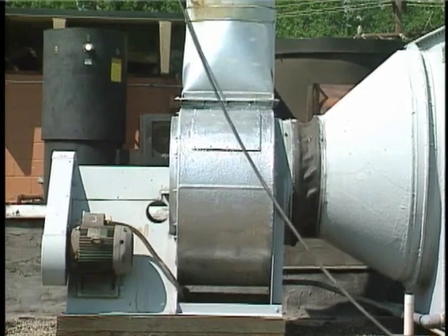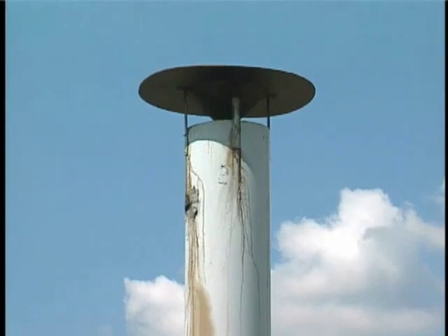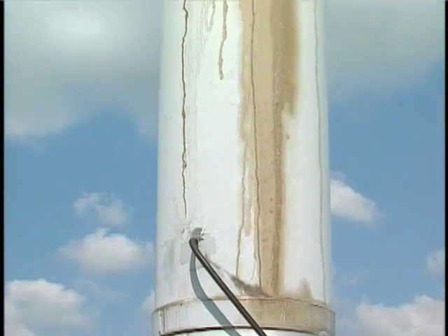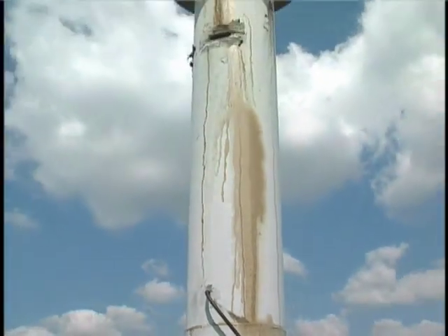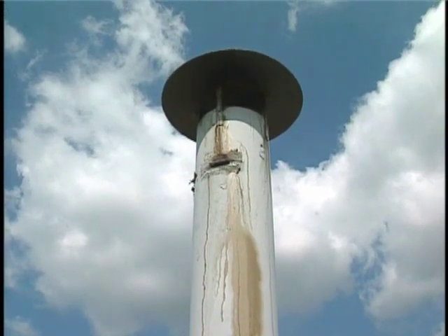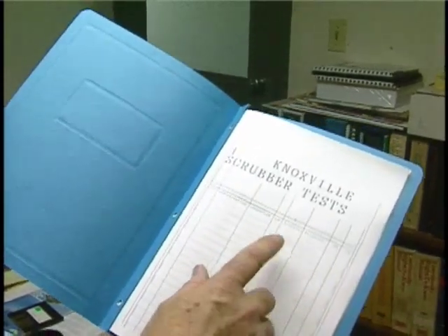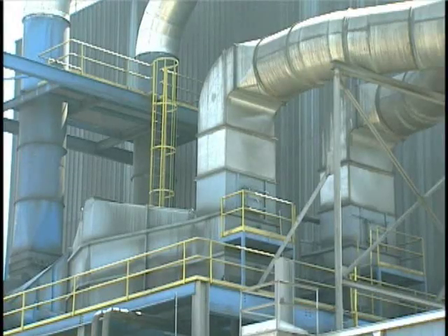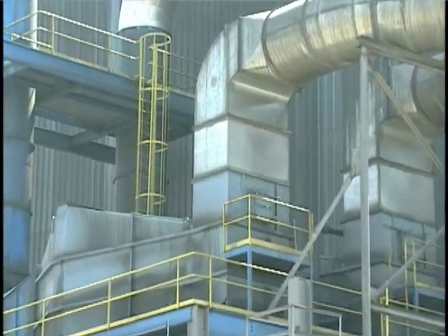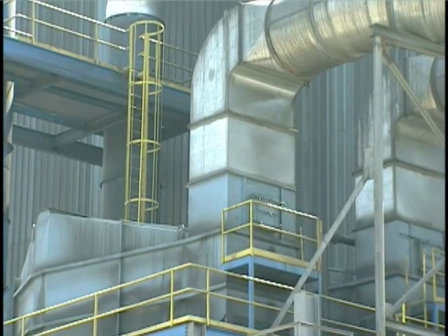The performance of the mist eliminator can also be evaluated by observing the stack and areas adjacent to the stack. Rainout of droplets around the stack, mud lips, and discolored streaks at the stack discharge, or heavy drainage from open ports, all indicate a poorly performing mist eliminator. Finally, component failure records should be evaluated. An increase from the normal failure rate indicates that the source should carefully evaluate the cause and correct the problem before equipment damage and excessive emissions occur.